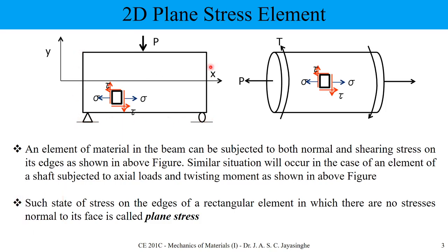Think about this kind of simple beam arrangement, a simply supported beam, and I am applying a load here. Here we are not applying any axial forces. Of course you can apply them, but here we are not going to. And here, if you cut out any small element, otherwise this is one point, the stresses at one point. If you think about the point stress of this system, what we can see is normal stress aligned with the beam axis and shear stress.